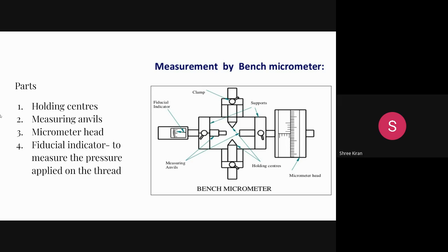Right? So the working principle of a micrometer is based on a screw and nut arrangement. Do you remember that? While we were doing the lab, they had a screw and nut, right? What happens if you tighten it more? It will just move on. So the working principle of the micrometer is based on a screw and nut, where rotational movement is converted to linear movement. The screw moves linearly by one pitch.